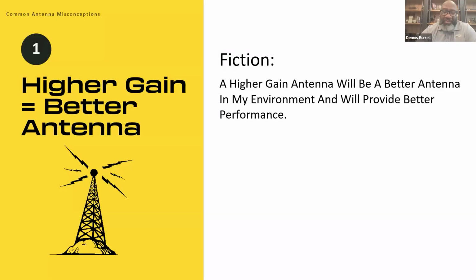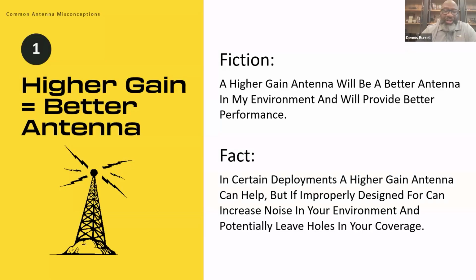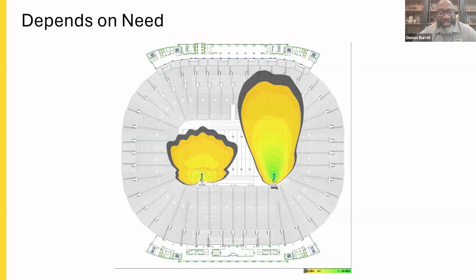In certain deployments a high gain antenna can help, but if not properly designed for, it can increase noise in your environment and potentially leave holes in your coverage. So the design of the antenna depends on the need.